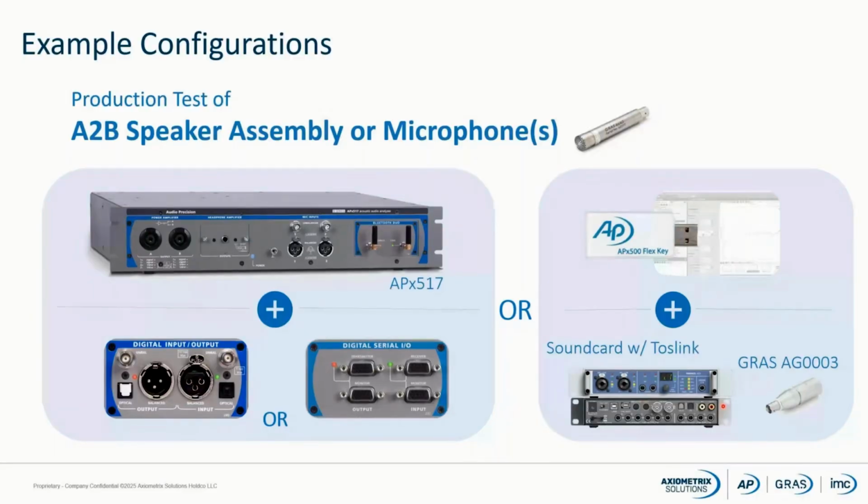If you are using a reference microphone and want to avoid buying a separate signal conditioner to power it, you can use our AG0003 adapter to power the microphone using the sound card's onboard 48-volt phantom supply.